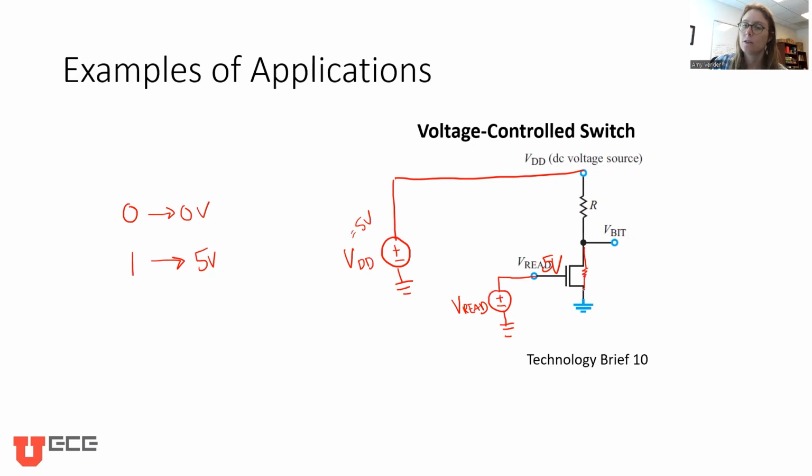And it has some small resistance, like 0.1 ohm. Since that's a lot smaller than R, I'm just going to approximate it as a wire. So then in this case, V out is now directly connected to ground, and current can flow because remember, grounds are all connected here. So V out is then equal to 0 volts in this case.